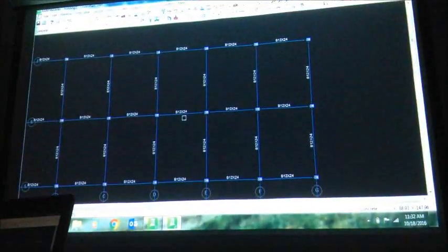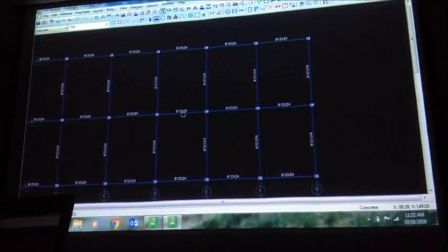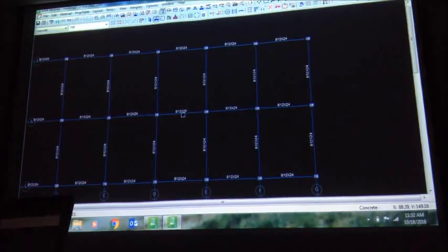Be 12 by 24. Do I click single or fence? For the assignment, you can do both, either single or fence. In real life, in a real structure, we will have multiple beam sizes, so in that case single would probably be better. Right now we are just using a general one, so just use fence.